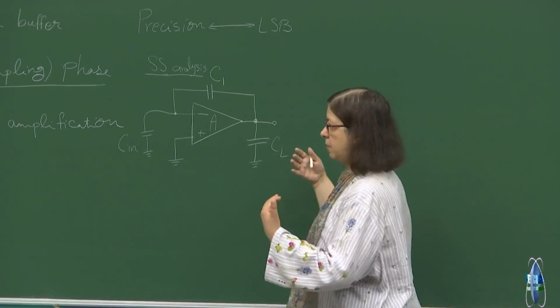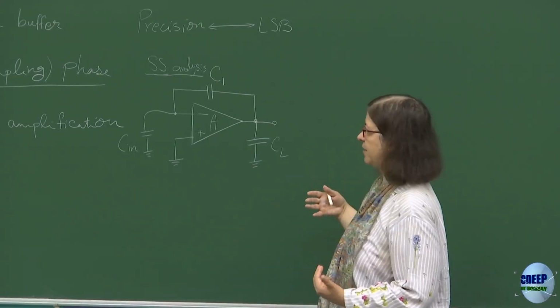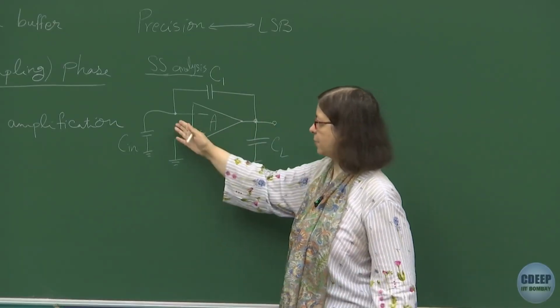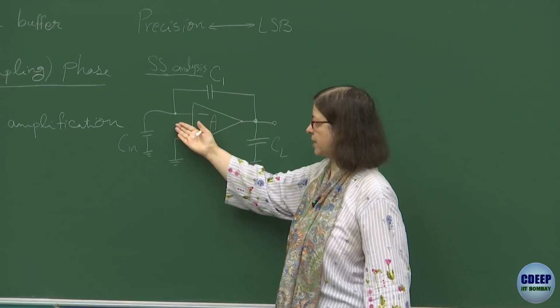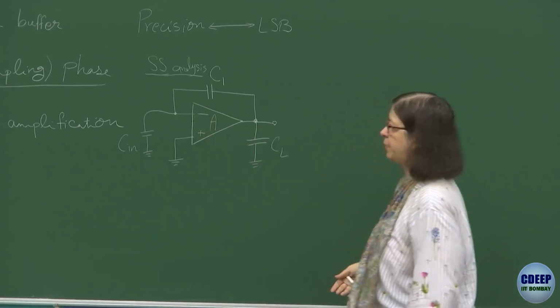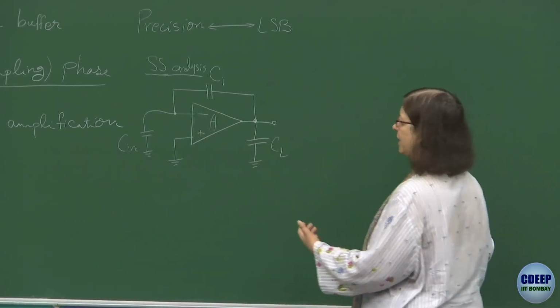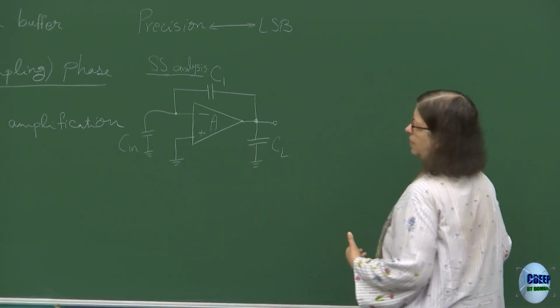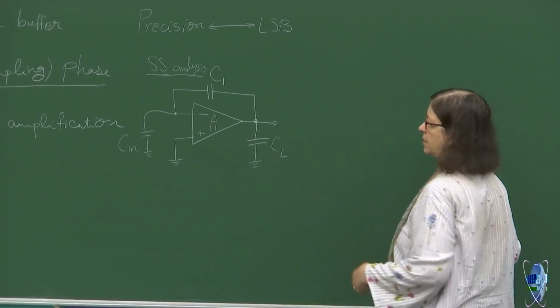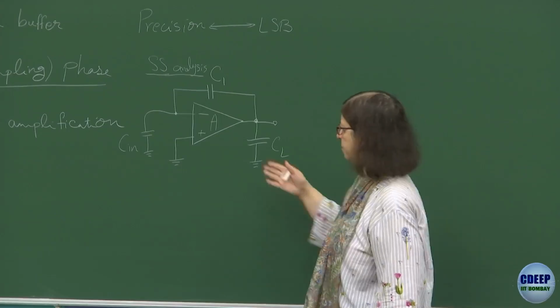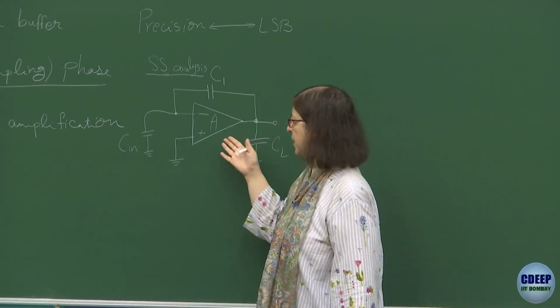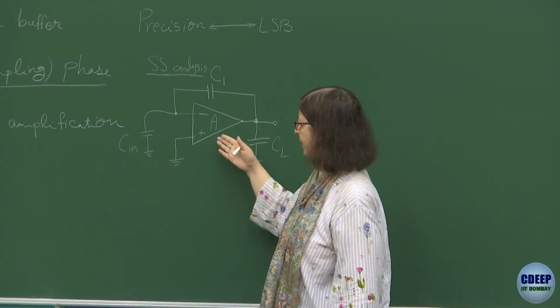After this slewing is settled, the op-amp gradually goes back. This node again will go back to 0. The op-amp gets into linear operation, and the remaining phase will depend only on the speed of the op-amp in the linear, or active, domain.